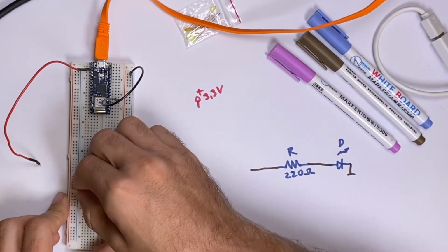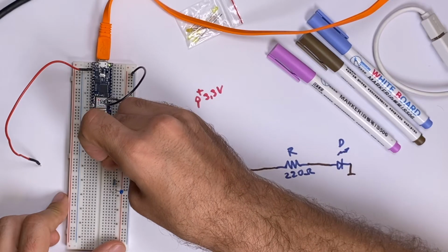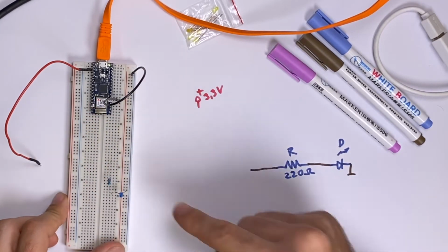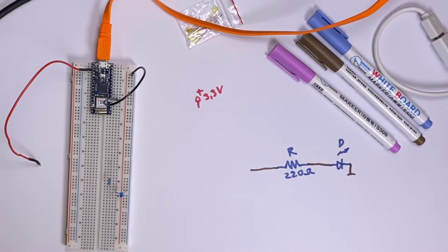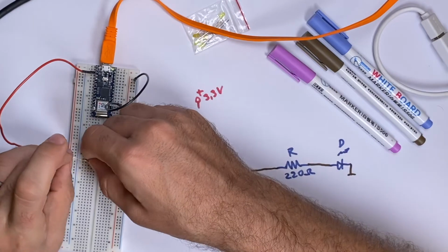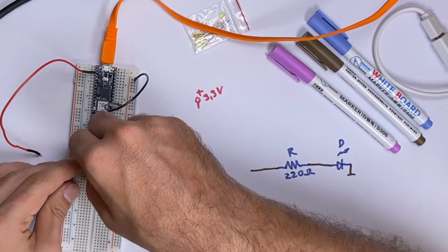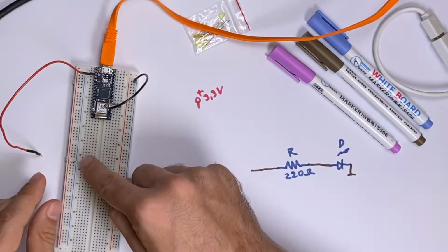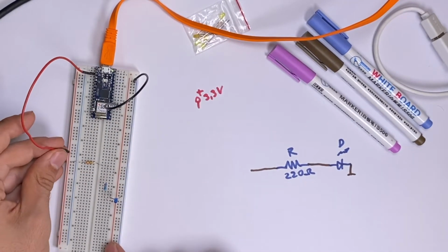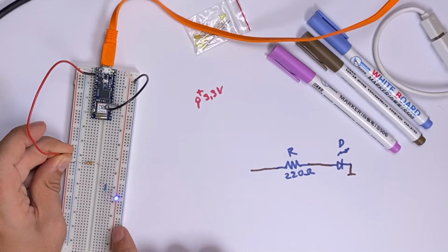But what would happen if I have 2 resistors instead of 1? So I will connect them in series, and instead of having 220 ohm, I will have 220 ohm and another value. So now I'll put that using 10 kilo ohms right now, but whatever other resistor, and let's see the intensity of the light. And it's dimmer. It's definitely dimmer. Before it was brighter.